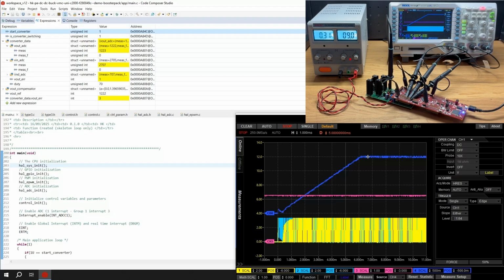You can also observe the current consumption on our DC supply. So now it is around 0.31 amps, and previously it was less than that, which confirms that we now have a different load. And you can also observe channel number 3, which is now high. In the previous case it was low, and this indicates that our load step PWM is set to 100% duty cycle.